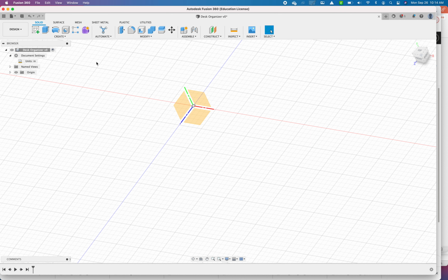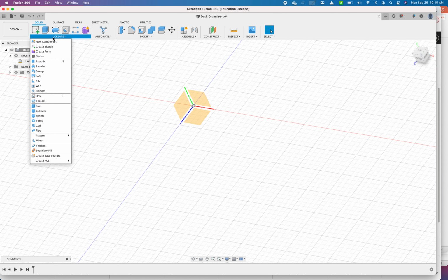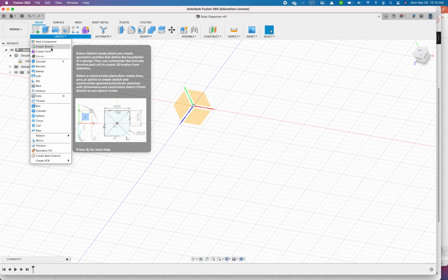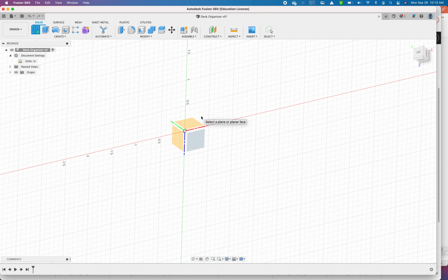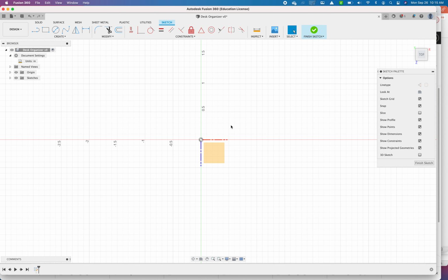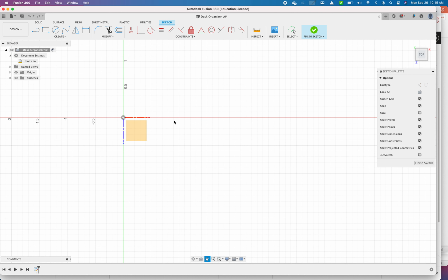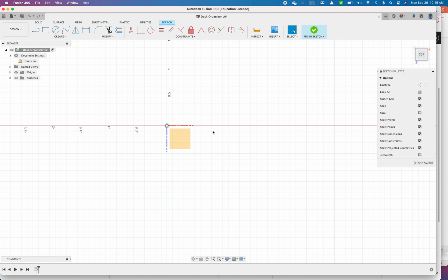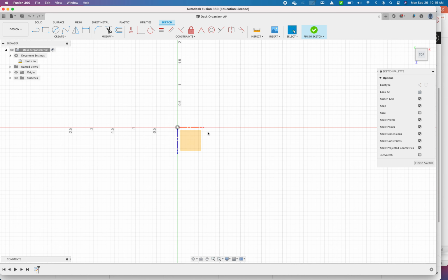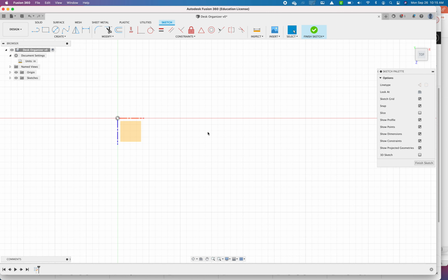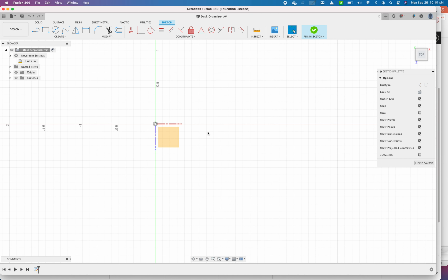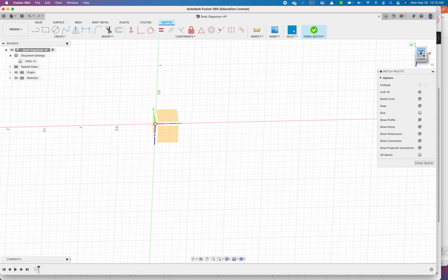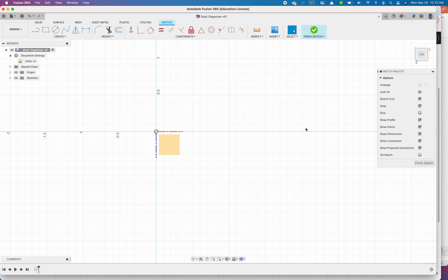We're going to start with a new sketch, which is this shortcut, or create sketch, and we're going to click on the base plane here. Once you're in a sketch, it's usually best to not orbit at all, so only using your pan, which is two fingers on your screen, or using zooming with the two fingers spreading apart and going closer together. But if you do orbit a little bit, you can use your view cube to get back onto a straight-on view.